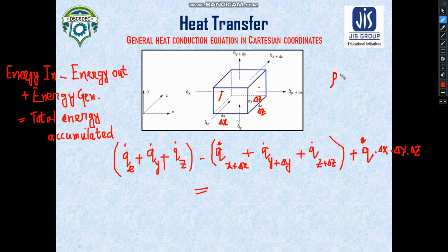If you remember the concept of thermal diffusivity, then we have already defined this term. So what was thermal diffusivity? We denoted it by alpha, and it was the ratio between thermal conductivity and heat capacity. The materials which have the tendency of storing energy rather than transporting it are said to be less thermally diffusive materials.